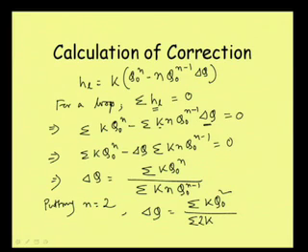So, we can write summation of twice K Q0, with n minus 1 becoming 1. So this power is 1. This is how we need to calculate delta Q. Now, while calculating delta Q, there is one important point: when we sum up this value, we know that the summation of head loss should become 0, meaning the correction should become smaller and finally become 0.